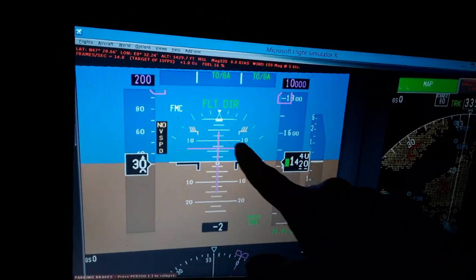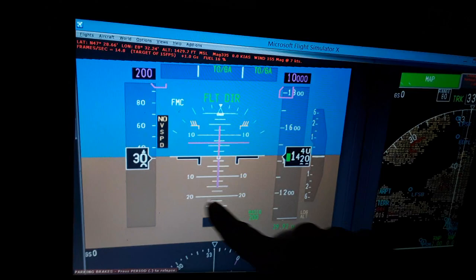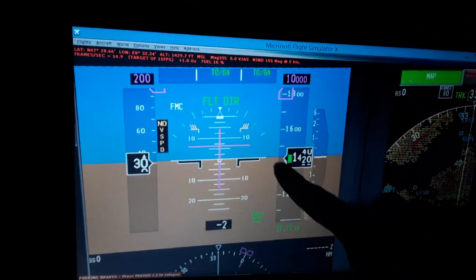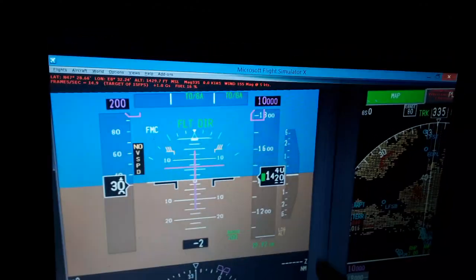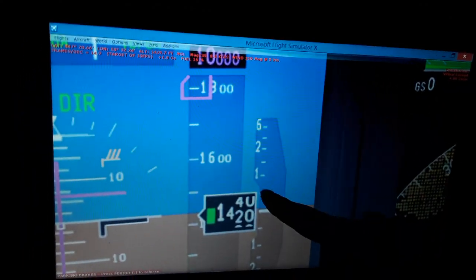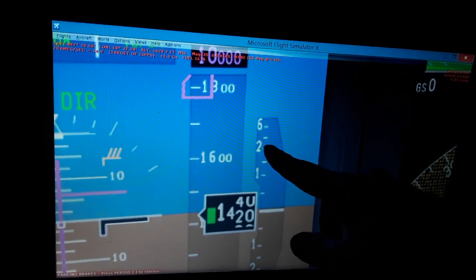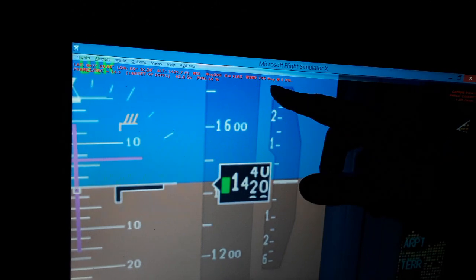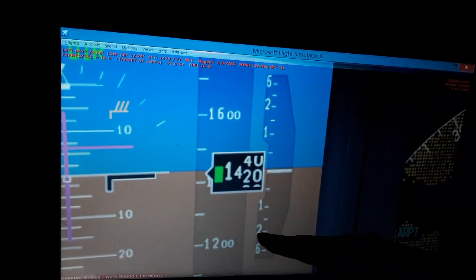Also the flight director here, the altitude indicator with the terrain and the sky color. Also we have a vertical rate of climb and descent of the aircraft in tens, hundreds and thousands of feet per minute. You can see 500, 1000, 1500, 2000, 3000, 6000 feet. You will see this needle moving up when we climb, moving down when we descend; it is the vertical speed indicator.